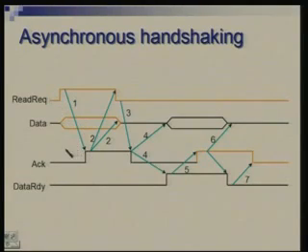We are not saying that it should come after a specific time. It could come after 1 nanosecond, it could come after 10 nanoseconds. What is important is that this carries a meaning. This acknowledge signal going from 0 to 1 indicates that memory has noticed that read request has come and it has picked up the address.